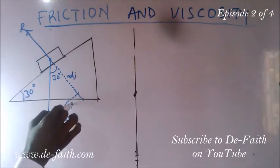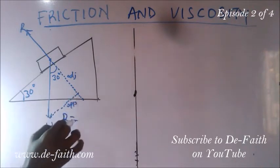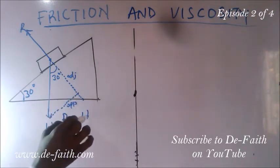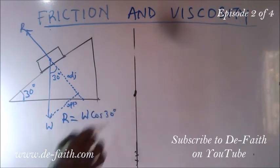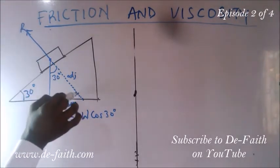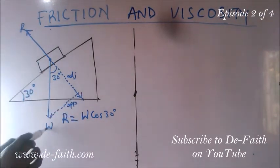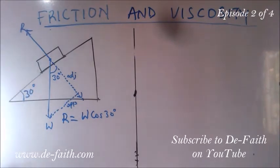This particular force here is going to take R equal to W cos 30 degree. So we have succeeded in resolving this normal reaction in this particular direction. Whatever R is here is also equal to this. So if we know what our weight is and we know this 30 degree, we can get this.